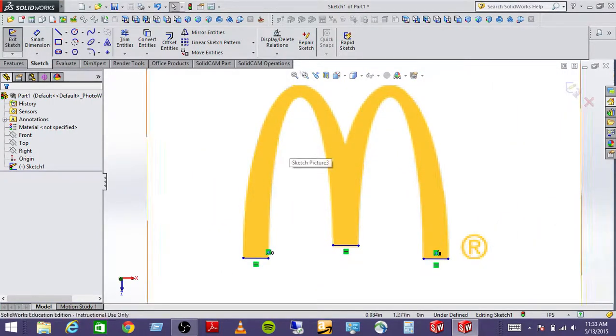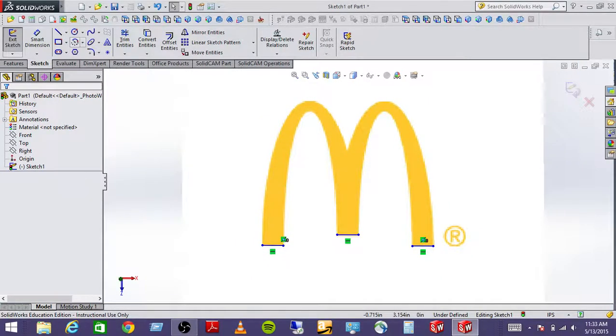Now, our problem is these guys. That's not going to fit a circle or a polygon or a rectangle or any of that jazz. It's probably not even going to fit an arc, a predetermined polynomial arc. But what it will do is fit a spline. So I'm going to show you splines. So click the spline tool. Now with the spline tool, you can click a multitude of points and then play with those points. I'm going to give you some hints though. All right.